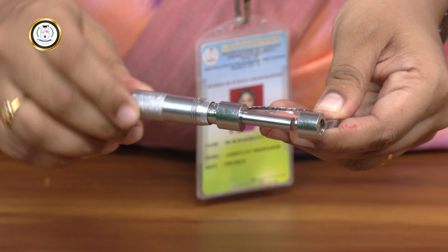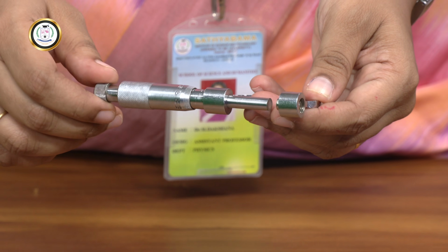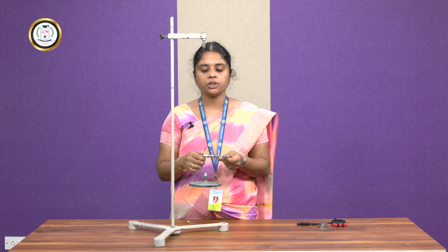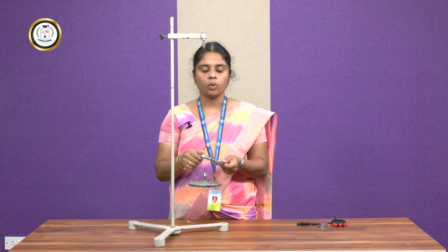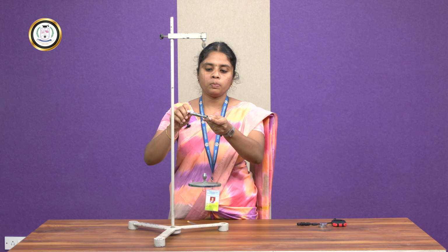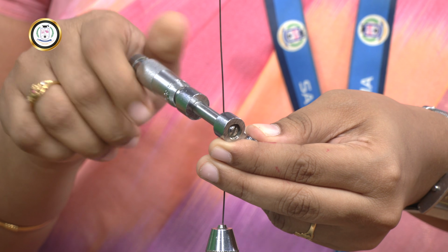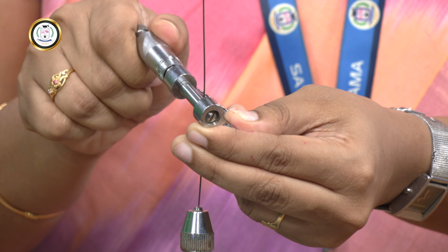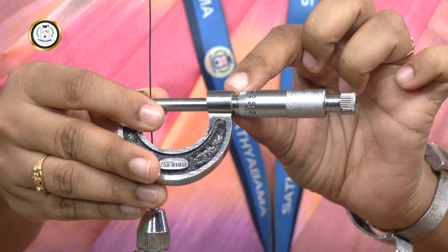We can begin measuring the radius of the wire by keeping the screw gauge at 3 different positions. Once you have found the zero error and zero correction, now we are going to measure the radius of the wire. To measure the radius of the wire, open the screw gauge using the screw given. Now we are about to place this wire between the 2 knobs in the screw gauge. After placing the wire in between, you can hear a tick sound, or you can give a good tight by placing the wire between the 2 knobs.